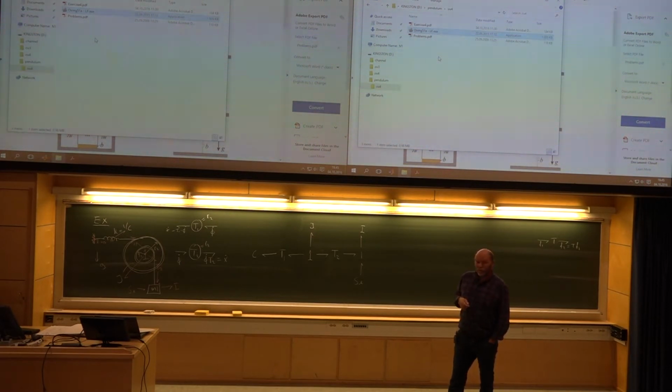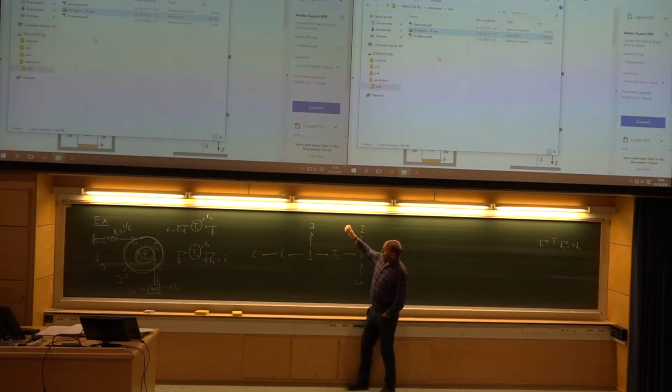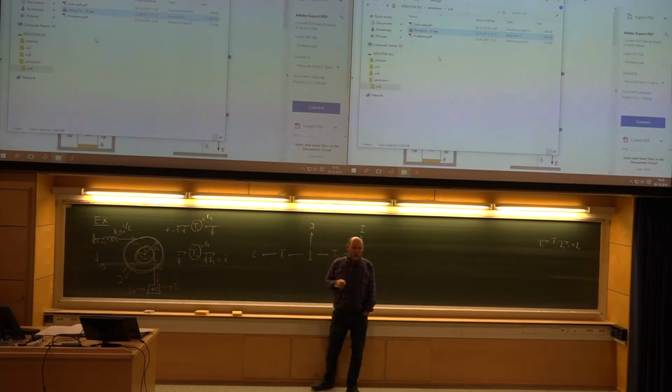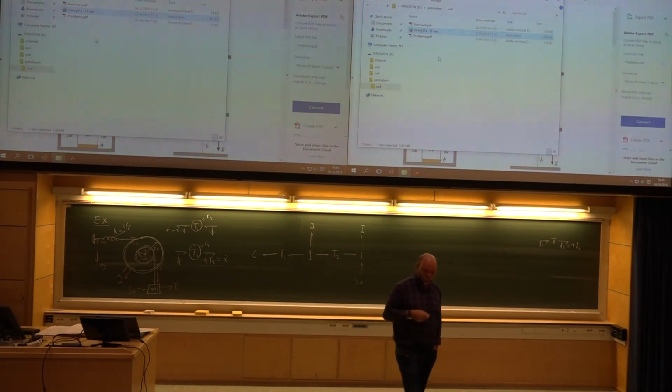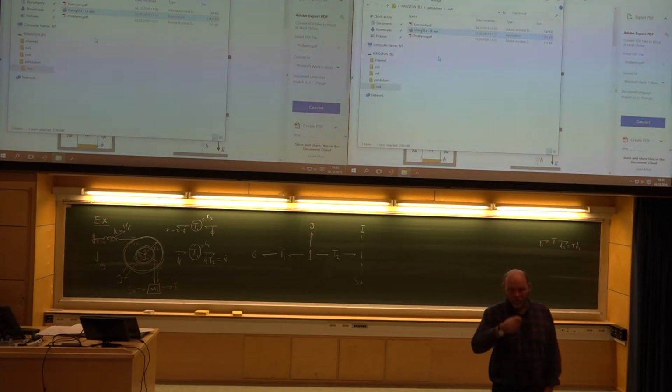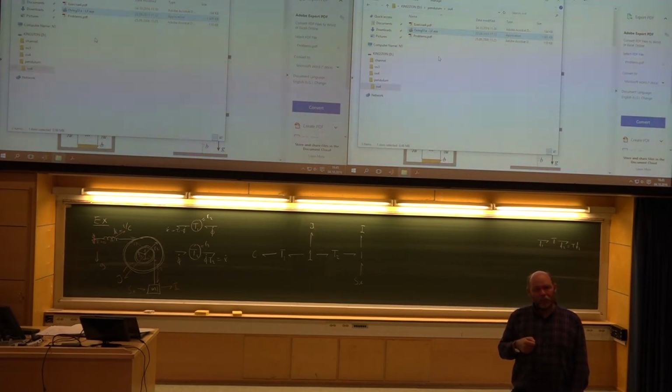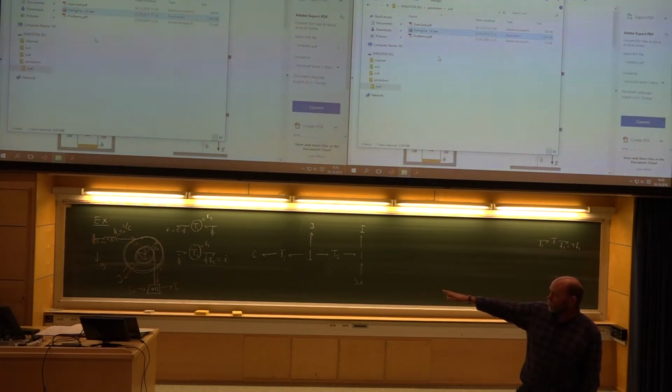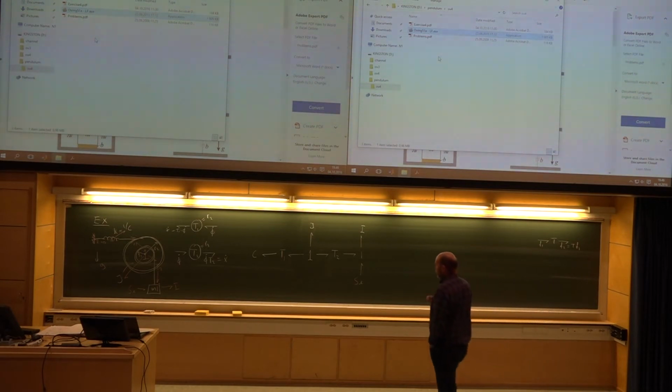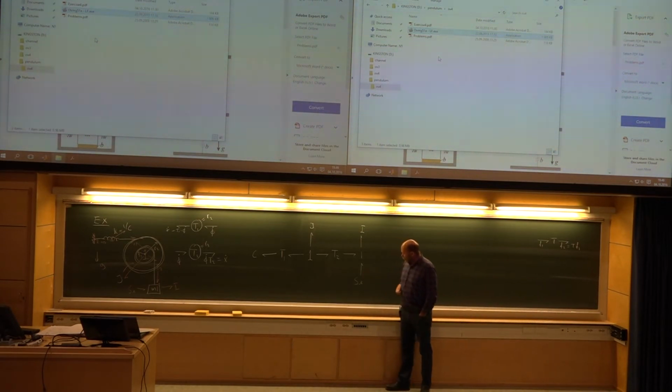Over-causal, what was that? Well, that was when one of the inertances or the springs got the wrong stroke. You got a differential causal stroke. When does that happen? That will happen if you have some direct coupling here. And don't we have that here? If you know the rotation of the wheel, then you know the speed of the mass m going up and down. They are directly coupled. Clearly, this is going to be an over-causal system. Let's try. Start with the mass.